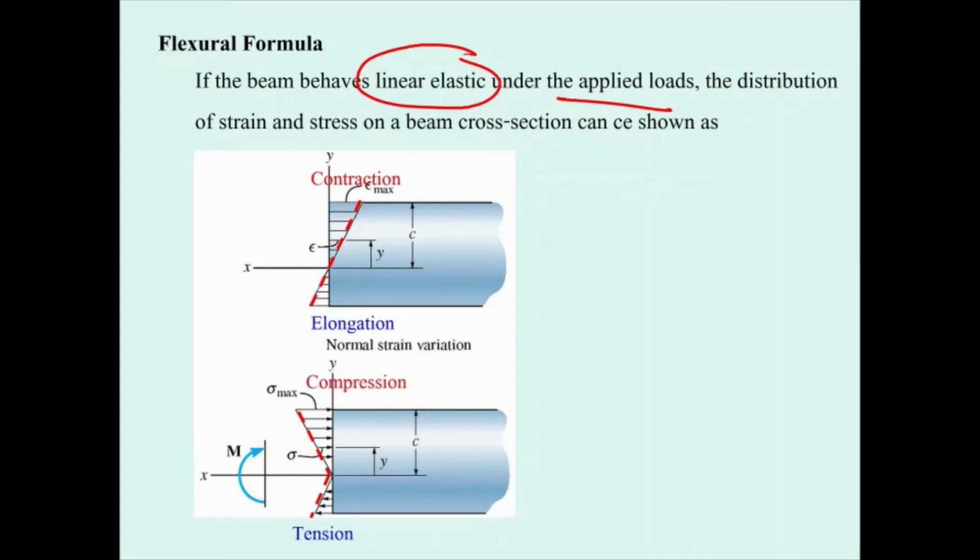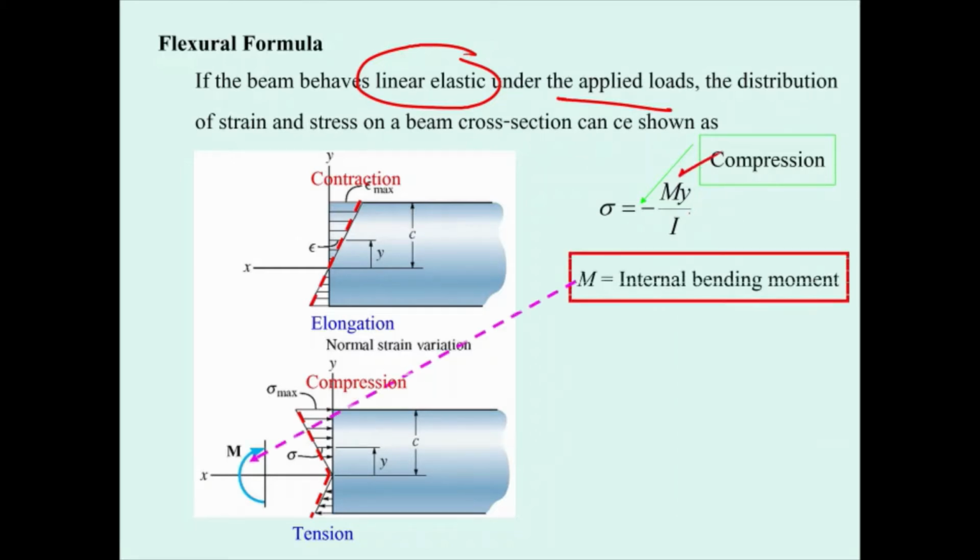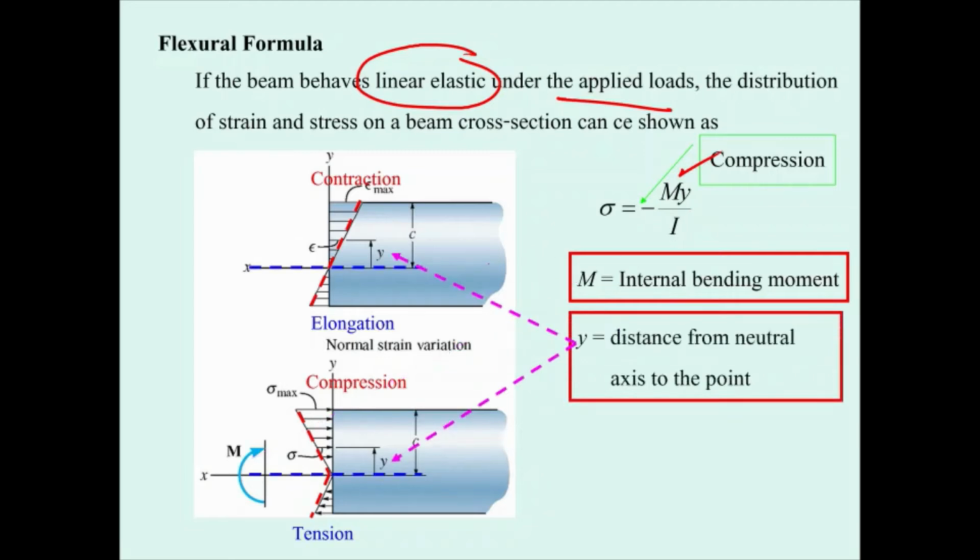Then we have the equation to compute the flexural stress, sigma equals M times y over I, where y is the distance that you measure from the neutral axis up to the point of interest. Since c is large, this will have the maximum stress, M times c max over moment of inertia. So the compressive stress is going to be larger than the tensile stress for this section.